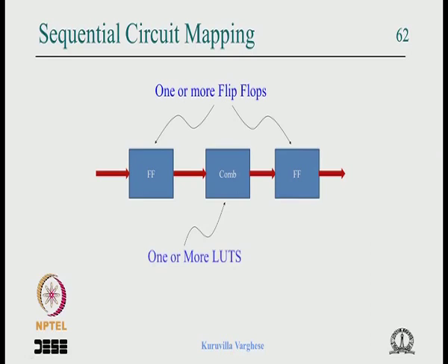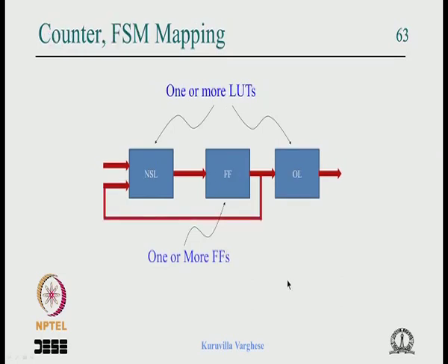Okay, and it will be good. The best we can hope is that this combination circuit followed by the flip flop can get implemented in the same slice. Depending on the number of flip flops, it might occupy multiple slices, and this would require some extra flip flops from a slice. It all depends on the complexity. Unless we see the circuit we can't say how it gets fitted.